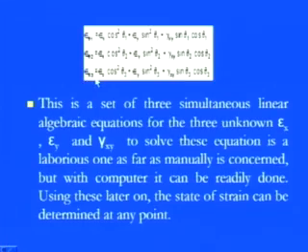So now we have epsilon theta 1, epsilon theta 2, epsilon theta 3, and as I told you, we can straightaway use those equations to compute them. We have epsilon x cos square theta 1, epsilon y sin square theta 1, and gamma xy sin theta 1 cos theta 1, which will give you epsilon theta 1. Similarly, we can get epsilon theta 2 and epsilon theta 3 just by putting in the values of theta 1, theta 2 and theta 3.